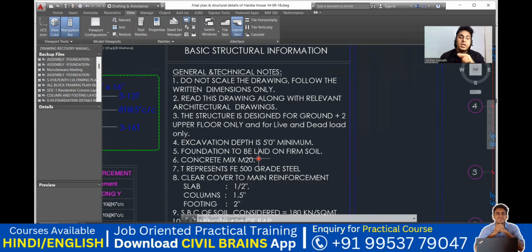Now the grade of rebar, since we are using RCC, it's a combination of concrete and rebar. So the rebar you're supposed to use belongs to FE 500, where FE stands for iron and 500 is the yield stress of that particular rebar.